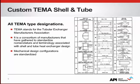And F-type can be employed when a temperature cross exists, which we'll discuss more later, and more than one tube pass is required. The G, H, and X are relatively rare, but can be utilized when shell side pressure drop is a limiting factor, for example. A J-type is typically used when shell entrance and exit velocities vary, as in a vaporization or condensation application, or an expanding or contracting volume of gas. The multiple inlets and outlets split the flow and reduce critical velocities within the exchanger.